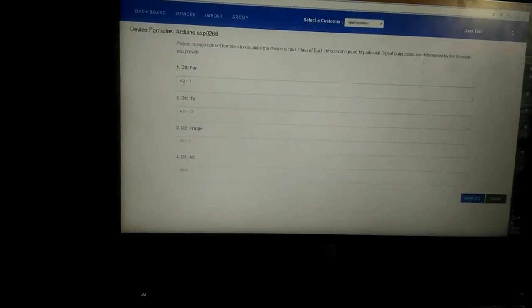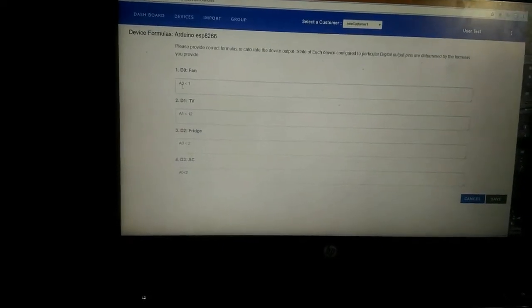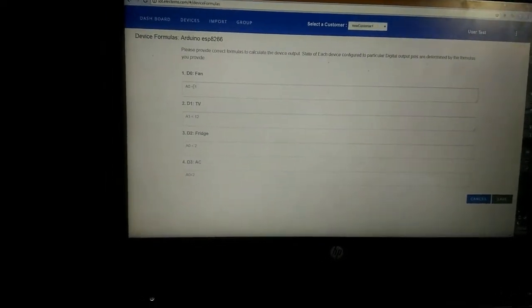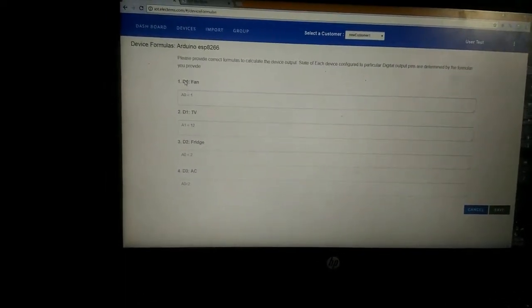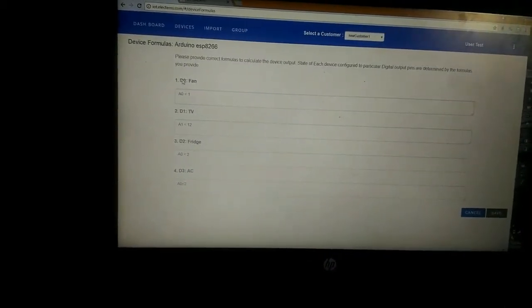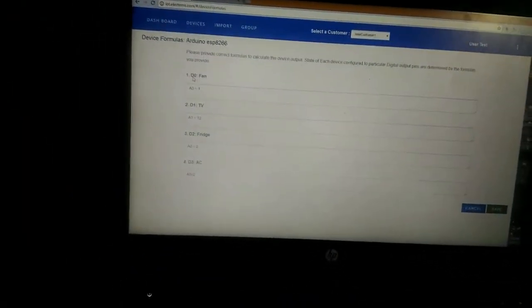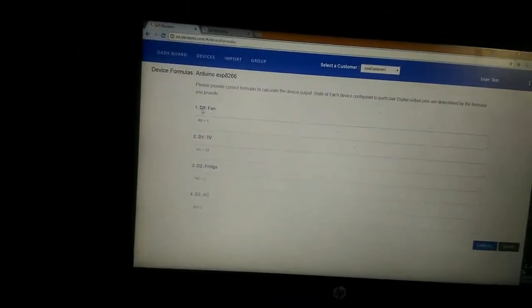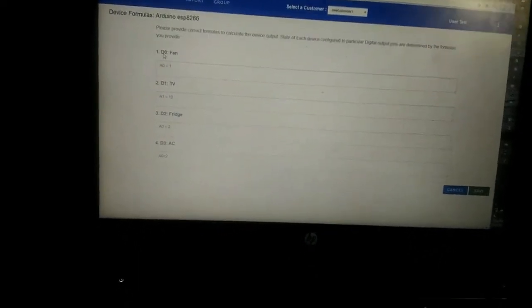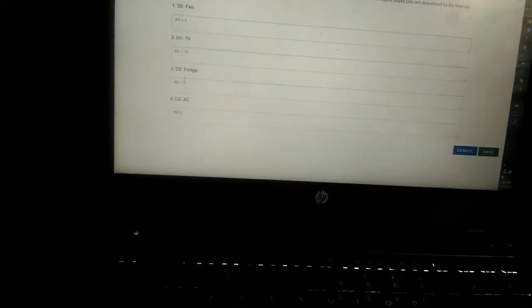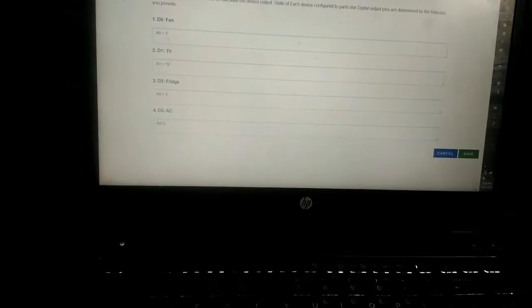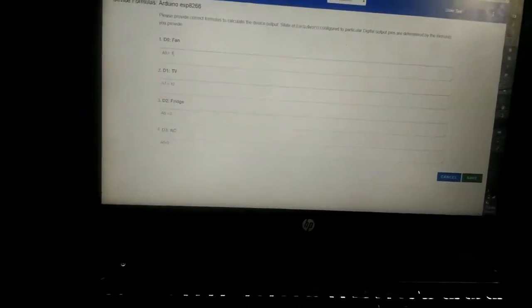So it will continuously measure the A0 analog input, and whenever it's lesser than 1, it would turn on the output bit of D0 or that particular relay to a higher value, which will turn on or turn off the state of the relay, which in turn would control your machine or your device, fine. So similarly, you can define any kind of formula based on the 16 analog inputs with different combinations and control your machine. Okay, so that's what we try to do here.